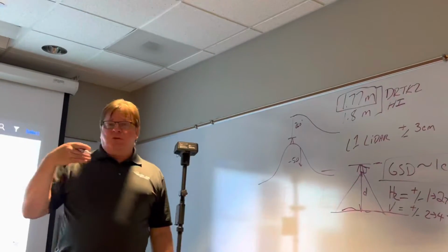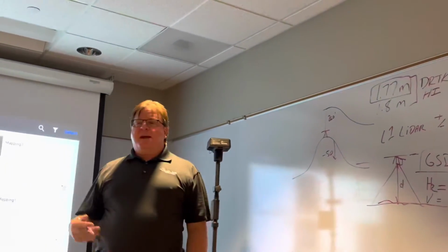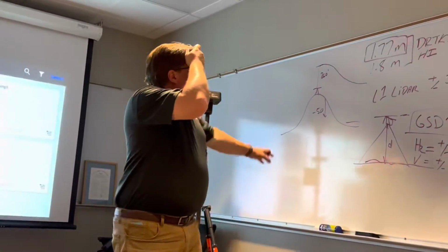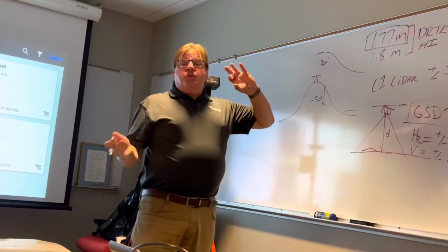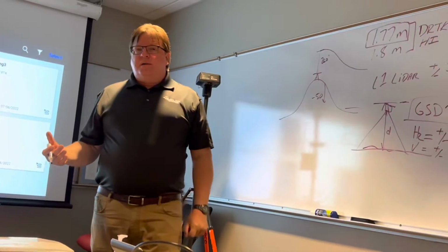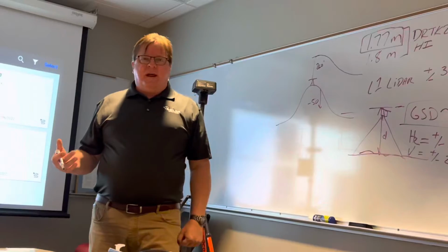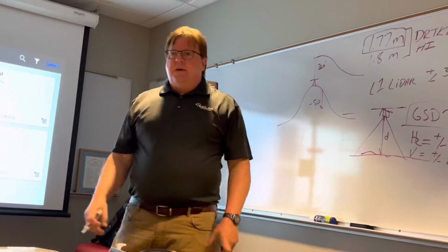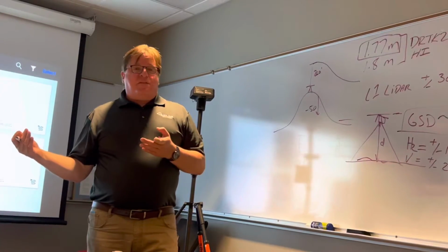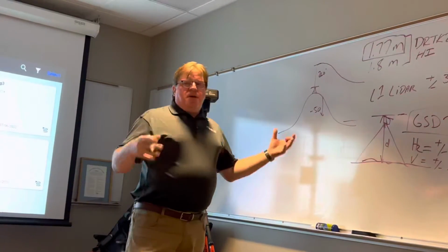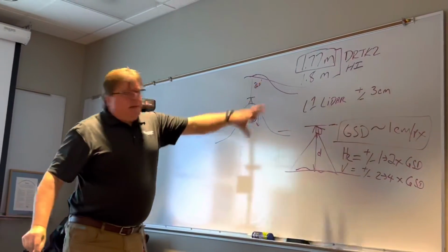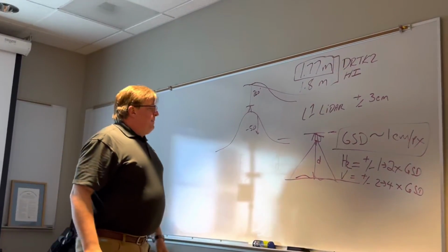I'm going to get an average overall ground sampling distance, so I can make a guess on my average overall accuracy. But if I wanted to, I could load in a model, a low density GeoTIFF from the National Geodetic Survey or USGS, and then tell the software to follow the terrain. It'll be like a 30 meter by 30 meter grid, so it may follow like this or something, but at least it'll get closer.